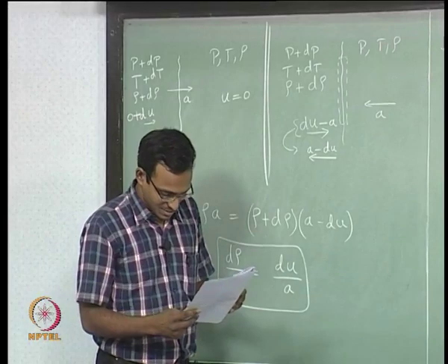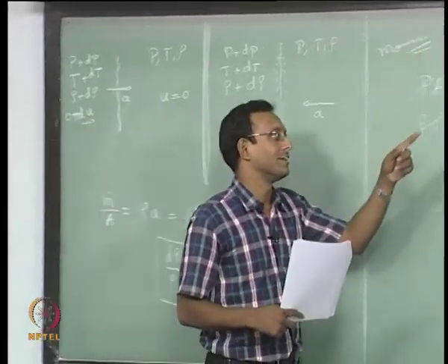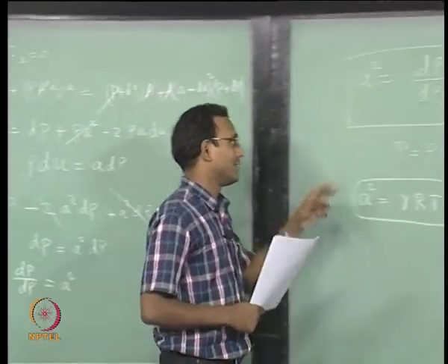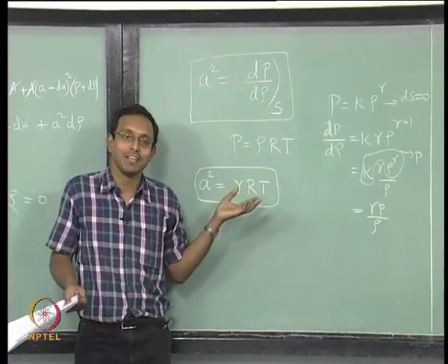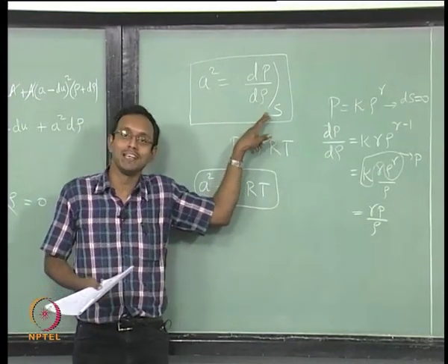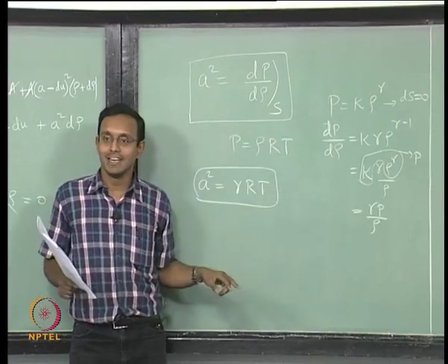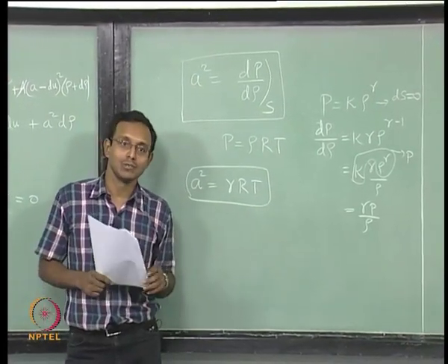Of course, I did some hand-waving argument in the end there, where I said I am assuming a weak wave and that there is not much heat transfer happening anywhere across the fluid elements, and so I am going to assume this to be roughly isentropic. In reality, pressure waves can be proven to be very close to an isentropic condition.